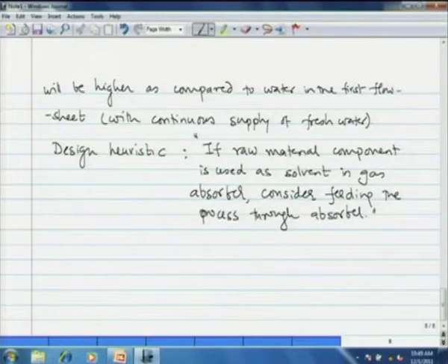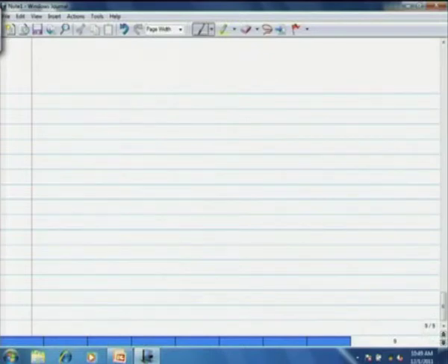So, the option of recycling of water has given us two flow sheets. Now, we do not know at this stage which one is the cheapest, therefore, we have to design both of them. So, that completes the level 2 of design, the input output structure. Now, the next stage is the material and energy balance.